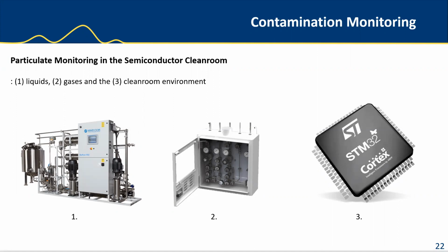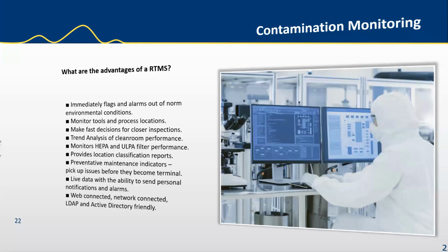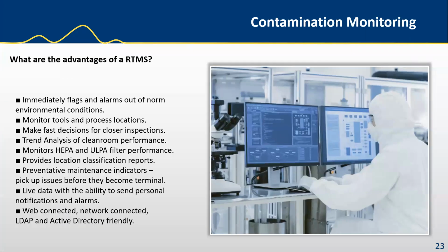With the advances in technology, real-time monitoring systems, or RTMS, that incorporate liquid, gas, and environmental monitoring are ideal for such applications because they give you the data in real time of different processes and different areas of the clean rooms, and also the introduction of clean water or gases and the environment itself where the wafers are processed. So real-time monitoring enables faster decisions to be made.